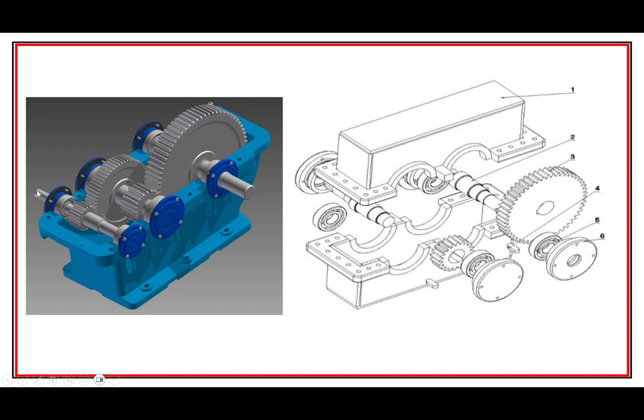If you look at the path, the power is going to be constant all the way through. Power in equals power out, but the torque is going to be small and the speed high right here. So we're going to have a path that comes in through here, transmitted into there. Now the speed reduces, but the torque increases, and then it's transmitted through there, and then through here, and then through there. So you can see the load path, where the energy is being transmitted. And so we're going to have slow speed here and high torque, but the same power.